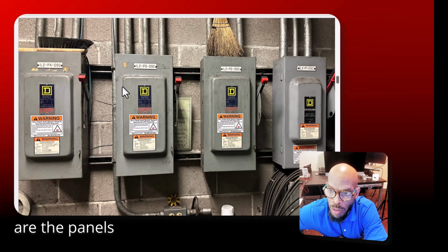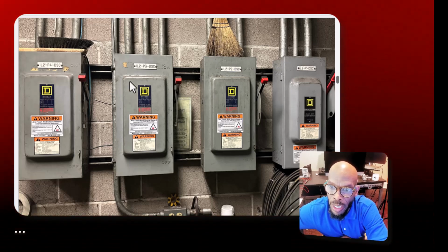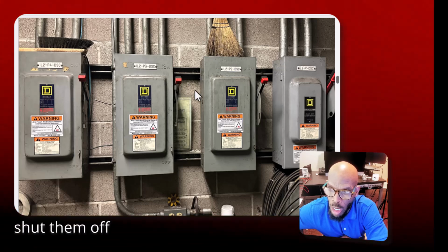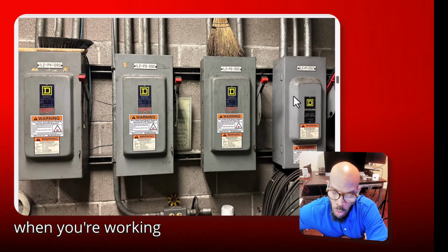Okay, so here are the disconnects that you just saw. And there's 4 of them. They get their power from the MCC also. And you can shut them off so you won't have to go up to the 3rd floor when you're working on them.